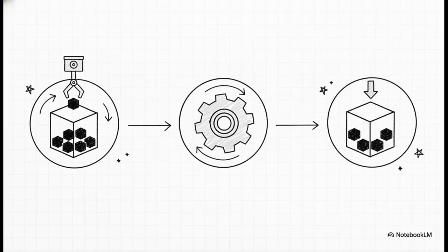It's just brilliant in its simplicity. You don't have a single messy command that tries to fetch data from memory, add a number to it, and put it back all at once. By enforcing this strict rule, copy a value from memory to a register, do the math on the register, move it back to memory, the CPU design is heavily streamlined. It allows for a few very simple addressing modes and, most importantly, totally predictable instruction times. This makes the design of the whole system incredibly elegant.